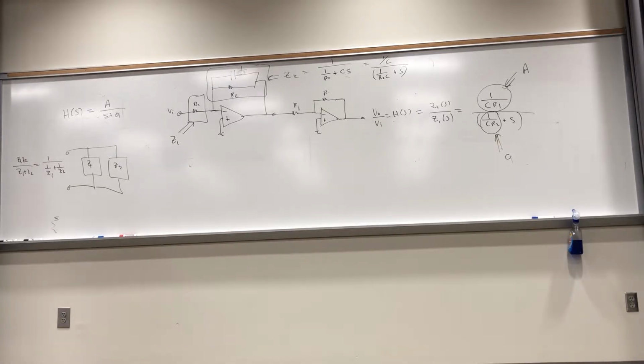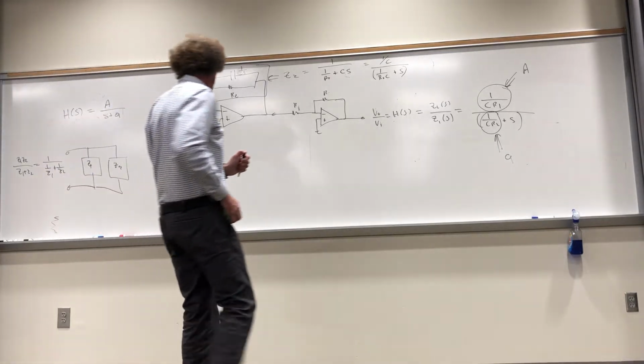All right? One other thing I'm going to say, remember this. You don't use inductors with operating circuits almost ever, unless this is going to represent the impedance of an antenna, or you're getting something called a resonator effect. Don't ever assume to use inductors. The reason is inductors don't work well in microelectronics. All right? With VLSI technology, we can make capacitors and resistors very easily. Inductors themselves are a problem. Just remember what I'm telling you. Use capacitors and resistors. So that's a simple pole.